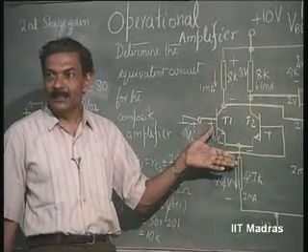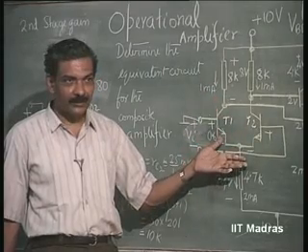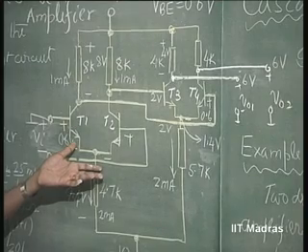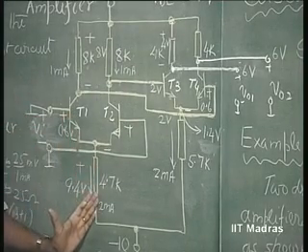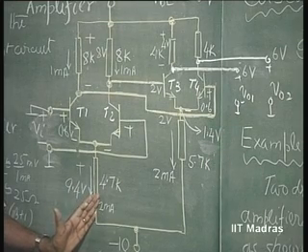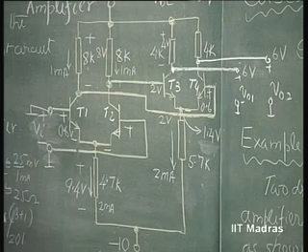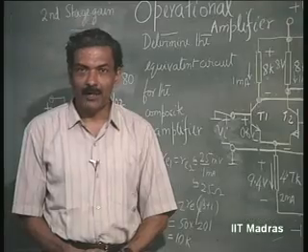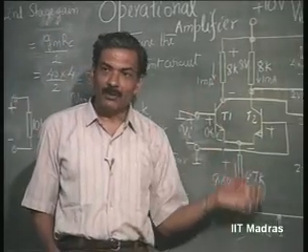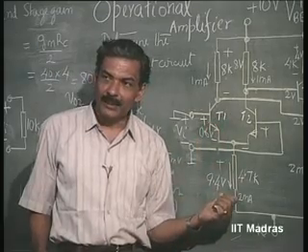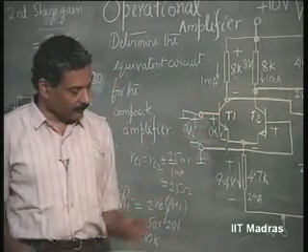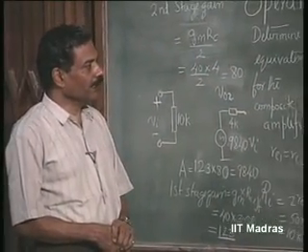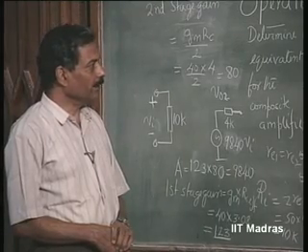Of course, gain is going to be reduced, this stage gain is going to be reduced, that is the price you are paying for making the input impedance high. So, whenever I try to boost up the input impedance by making the current low here, the gain also falls. But the first stage of any amplifier has major responsibility of not gain, but input impedance and common mode rejection ratio. So, we do not bother about the gain reduction here, we purposely make this operating current very small and this voltage very small. So, this is the situation of design in what is called operational amplifiers.